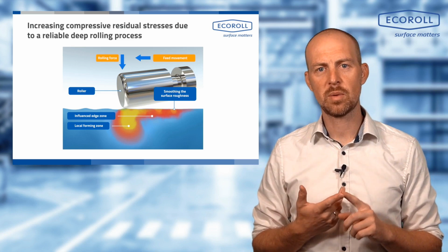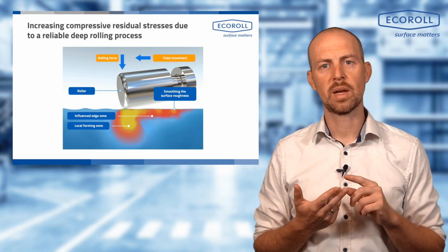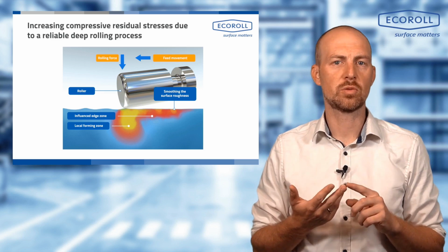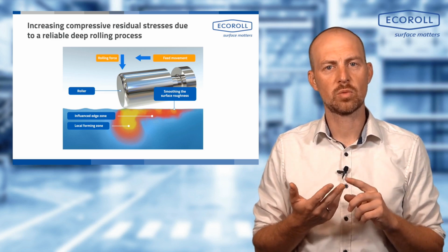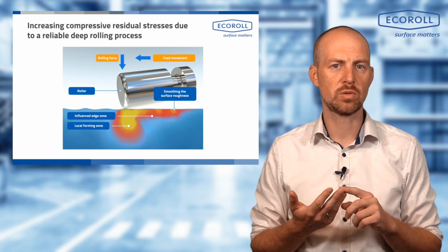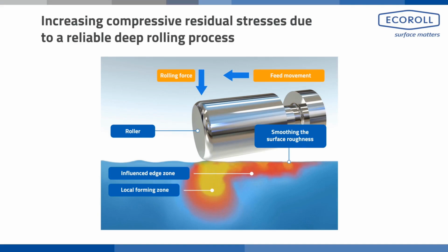We can make errors when measuring the tools. We can make errors during the pre-processing. We can have temperature adjustments. We can simply define the rolling force incorrectly. We can set a wrong programming for the delivery. There are various parameters that we can change to alter the rolling force. However, we do not see it in the process results.